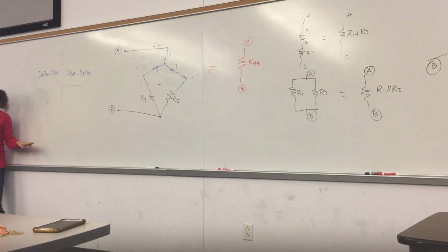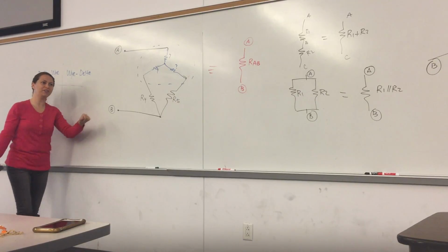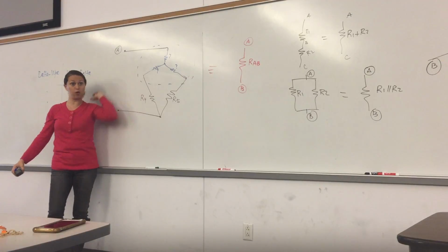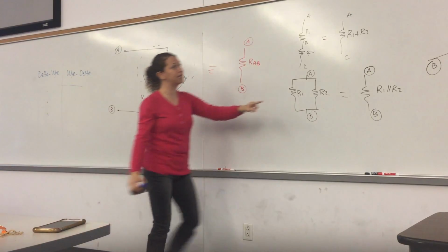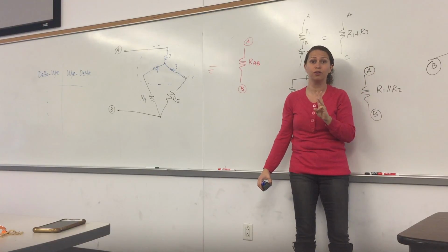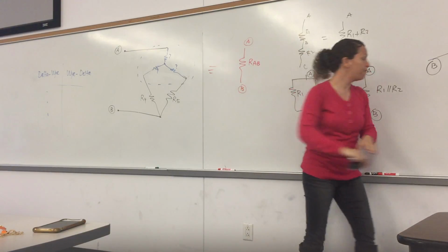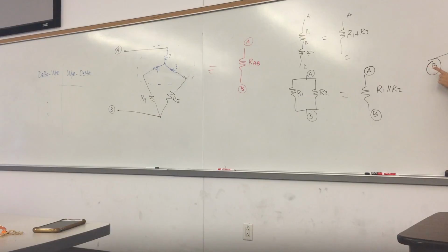Why three equations? Three unknowns. The resistors. Because there's three. Almost, right? Fair enough. The three equations, because when you look into that delta, I can define three equivalent resistances depending on which two terminals I look at, right? If I'm looking at the terminals A and B, what is the equivalent resistance in between A and B? RC, with C not connected anywhere.